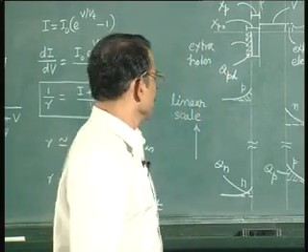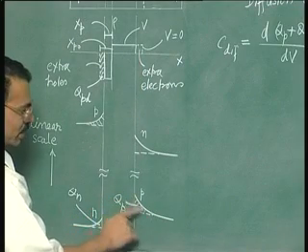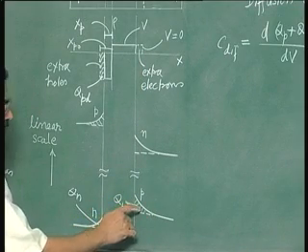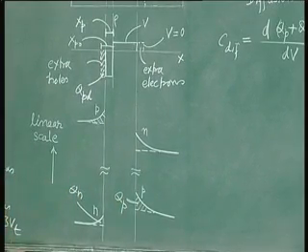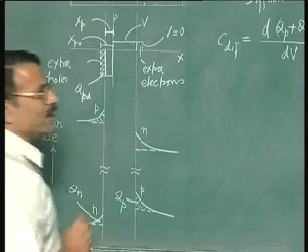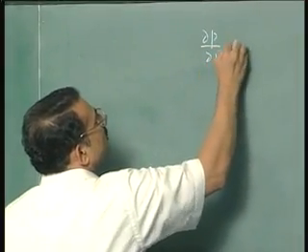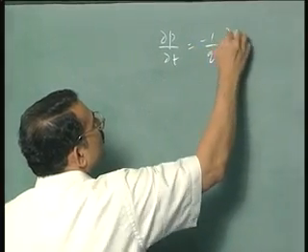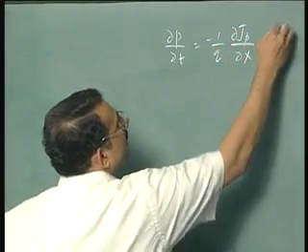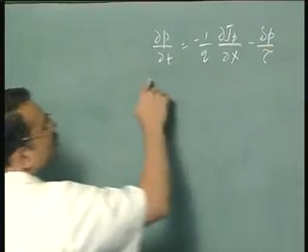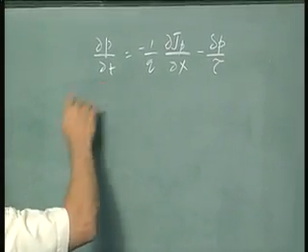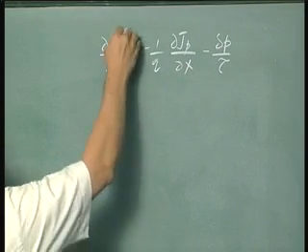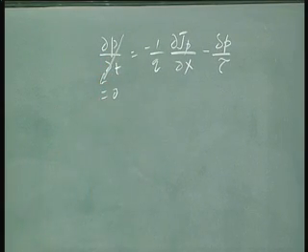For example, if you want to get this exponential distribution, then you take the continuity equation for holes and you are going to set dp/dt in the continuity equation to be 0. Let me write that equation here to show this. So dp/dt is equal to minus 1/q times djp/dx minus delta p by tau. This is the continuity equation for holes on the n side. To get the distribution of holes, you are going to set this equal to 0 under steady state conditions.